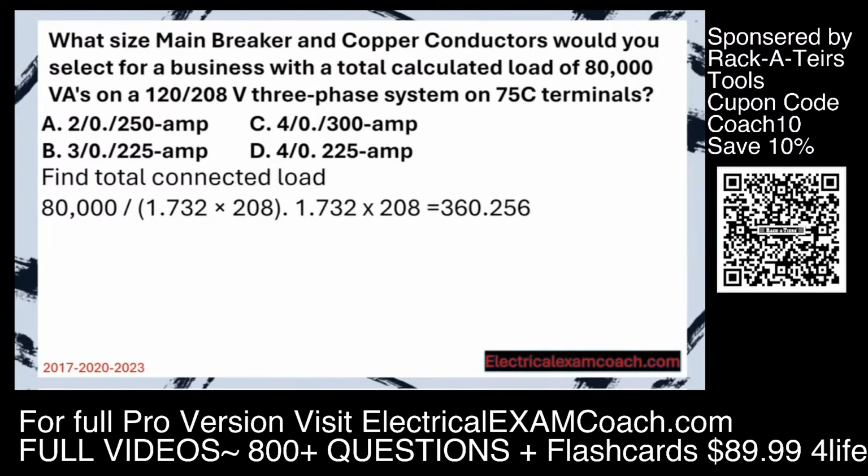We take 1.732, multiply it by our system voltage, which is 208, and that gives us that 360 value. Now we can divide just like normal. We take the 80,000 VAs, divide it by the 360, and that gives us a 222 amp known load by which we can size our breaker and our wire.